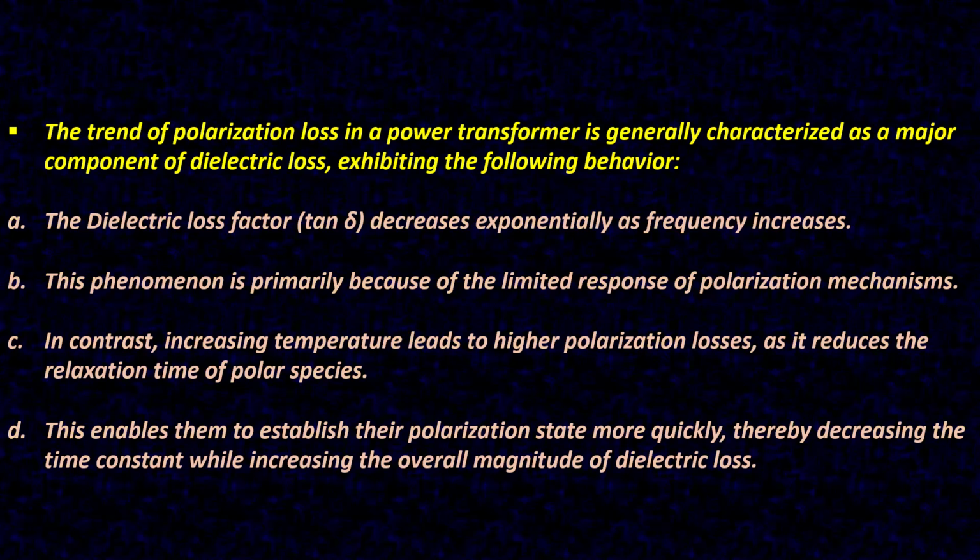A, the dielectric loss factor, that is tan delta, decreases exponentially as frequency increases. B, the phenomenon is primarily because of the limited response of polarization mechanisms.